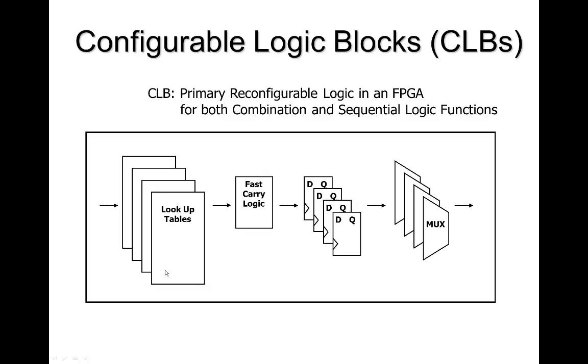If you think of a lookup table at its simplest, it could really just be the truth table of a gate, for instance. The larger the lookup table, the more memory it has, and the larger the truth table that you can implement right in the lookup table. And so that's how we're going to build it. That's our programmable element that we're going to use.